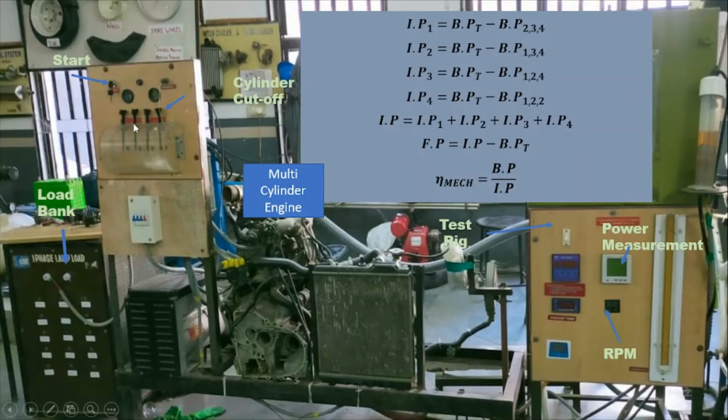Cut off the second cylinder, third cylinder, and fourth cylinder, and then do the necessary calculations. The first indicated power is the total BP when all cylinders are running minus the brake power when the first cylinder is cut off.